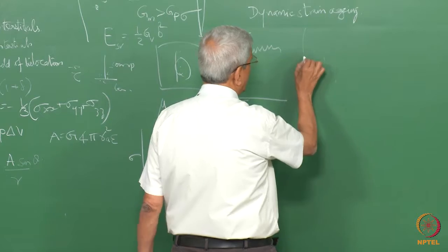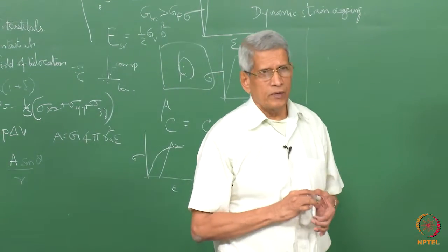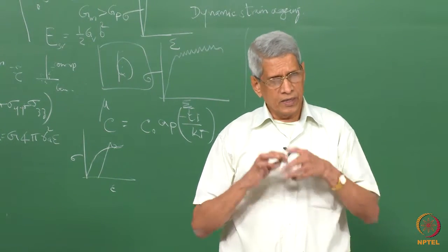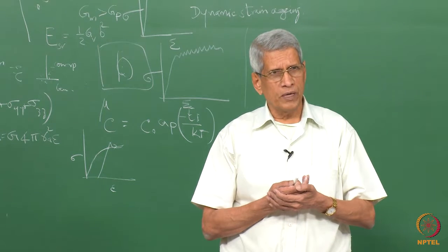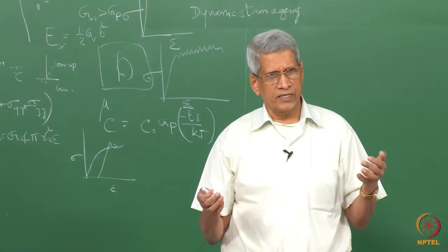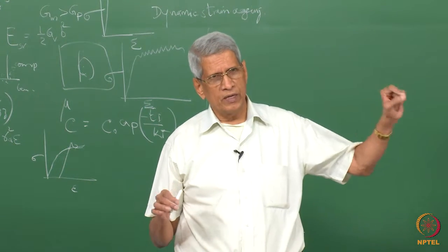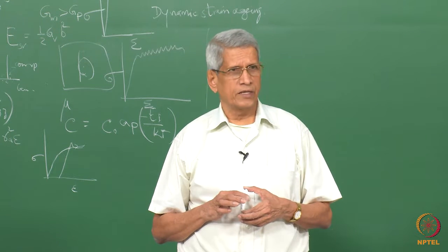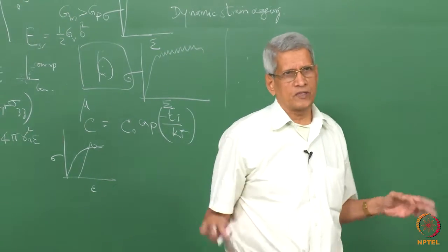Unless the dislocation is very close to the defect, there is no effect. Then it's called a local interaction. In some cases, the interaction could be a diffuse interaction, meaning a long range interaction takes place between the solute atoms and the dislocation. Both types of interactions can take place.